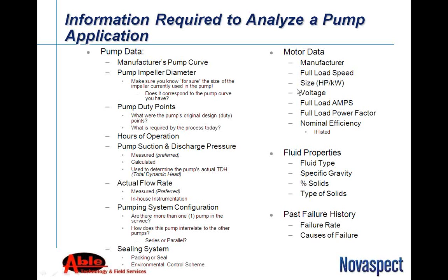Then going up to the motor data, you need to know the full load, the size, horsepower, voltage. You will need to know all this information. It's very critical in analyzing what's going on in your system.